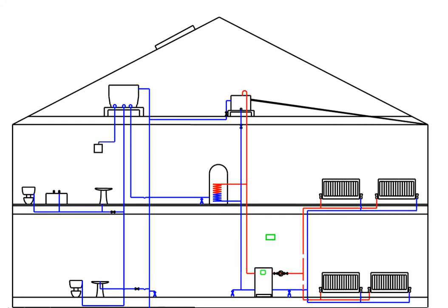Now we need to put in our controls. We have our main control center here with controls on the boiler, on the cylinder, and in the rooms. We also need a wire coming down here onto our circulation pump and a valve to close off upstairs and downstairs our throttling. So that's what the timer looked like in the room, or the thermostat I should say. There we have our controls inside the room, and we must bring our wires back then to the control center.